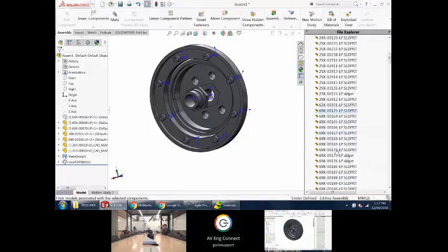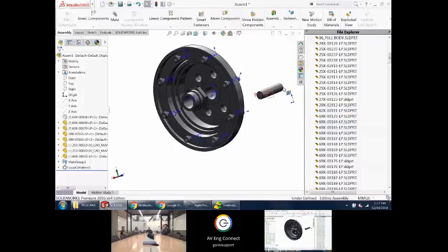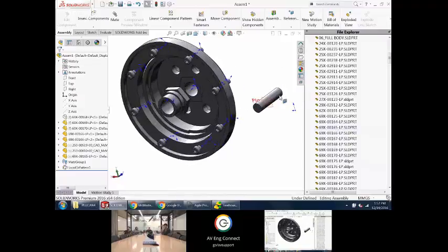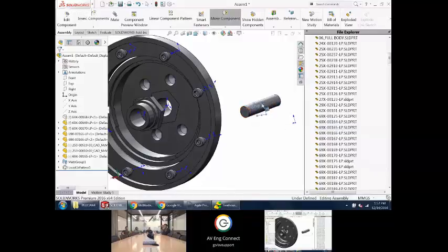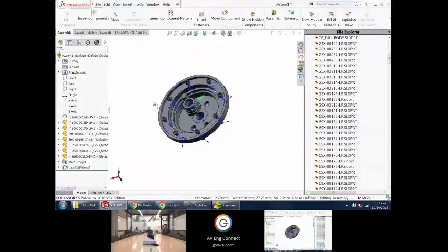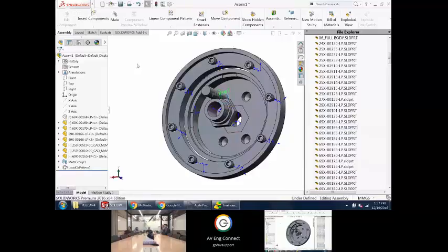Okay, another component. Hey, that's the one. I want this in here. Of course, I'm going to make my life easier on this one. At least I thought I was going to. Yeah. I pick this circular edge, hold down my Alt key, put it in there using the Peg and Hole SmartMate, my favorite. Another way to quickly populate items, especially if they're in a regular pattern, because you see this thing isn't actually a square, something like that. I could do a rectangular pattern, but then I'd have to keep up on it to make sure that it was spaced right.